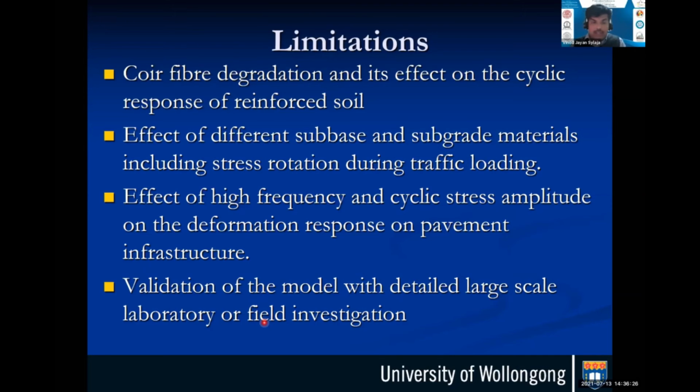for any infrastructure development. The effect of different sub-base and subgrade materials, including stress rotation during traffic loading, needs to be investigated. On frequency, we have only looked at around 1.5 hertz, which is very small for a traffic condition. And we need to look at a very high frequency and very high cyclic stress amplitude before applying this to any kind of pavement infrastructure. And finally, we need a large-scale validation of the model with detailed large-scale and field investigation, which needs to be done before applying this to any field application.